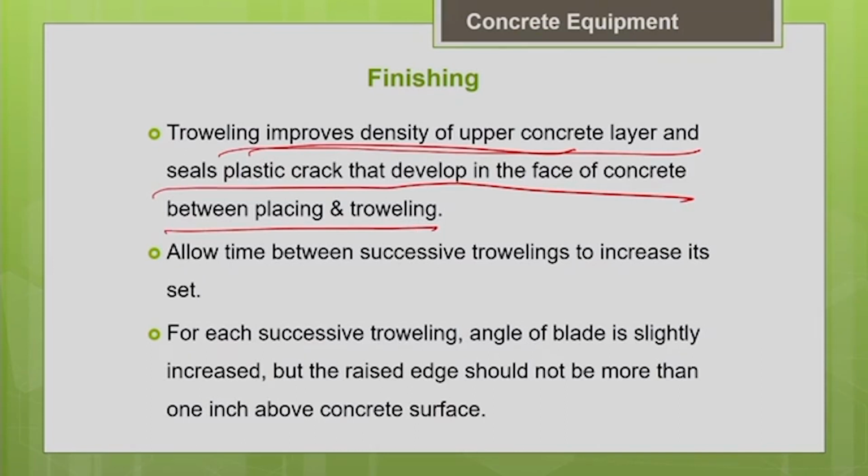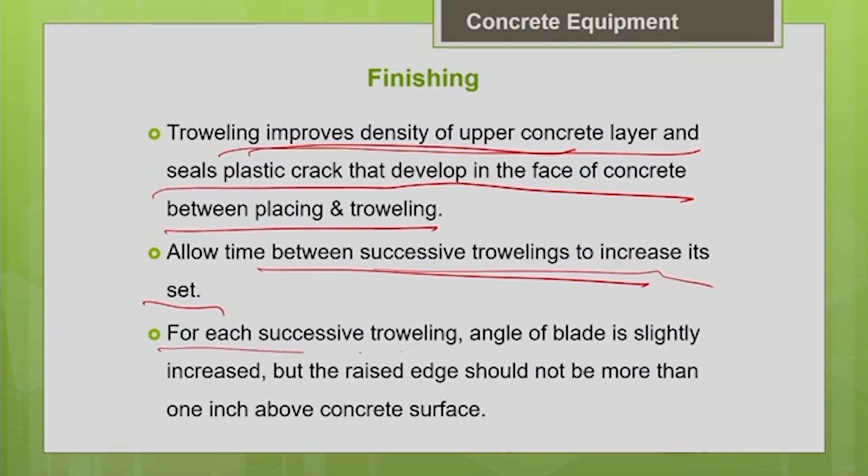As I mentioned earlier, allow a time interval between successive finishing operations, between successive trowelings, to increase the set. As the concrete dries up more and more, it is easy to smoothen and polish it. It will be stiff enough to receive the texture which you are going to offer to it. For each successive troweling, the angle of the blade is slightly increased, so that you can apply more pressure to the concrete.